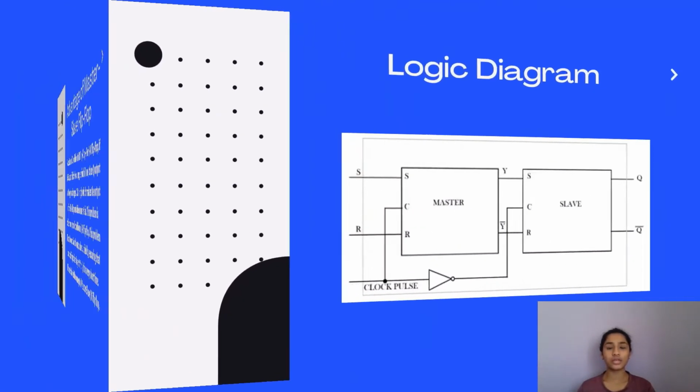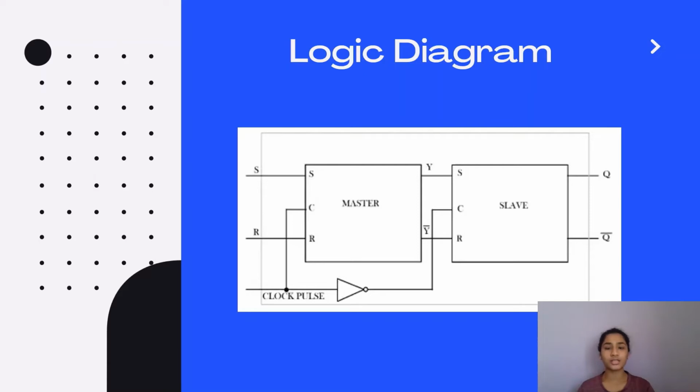So now let's look into what exactly is a master-slave flip-flop. In a master-slave flip-flop, we will have two flip-flops, where the first is called the master and the second flip-flop is called the slave. The clock pulse given to the master, the inverted clock pulse of that is what goes to the slave, as shown in the figure. Apart from that, the output that comes out of the master, that is Y, is given as the input to the slave. So this is how the master and slave work.